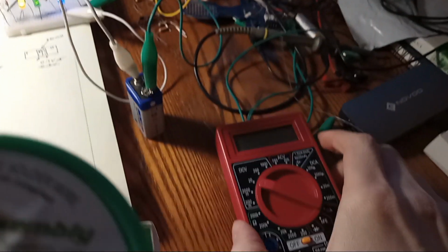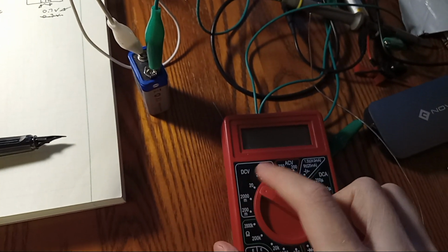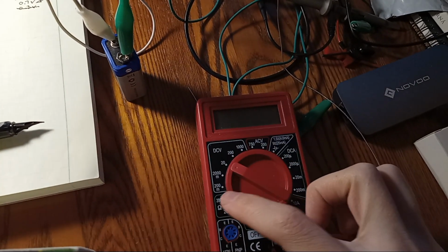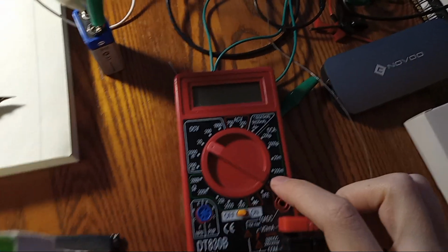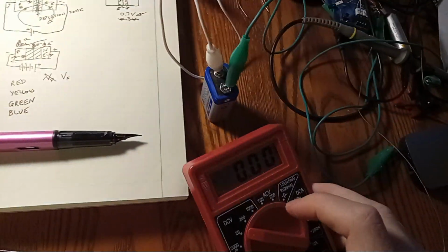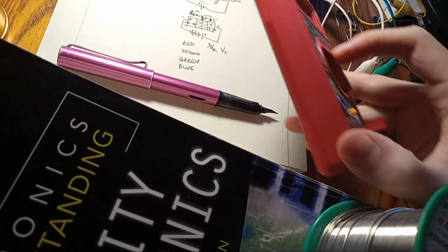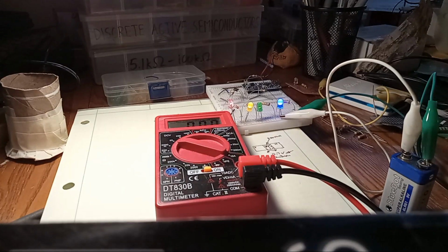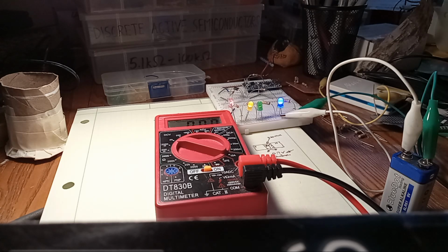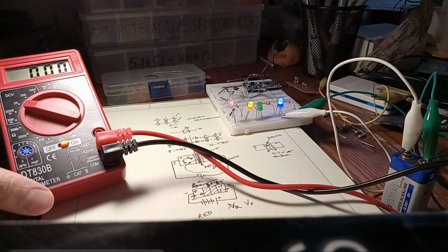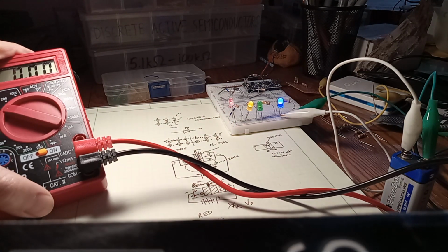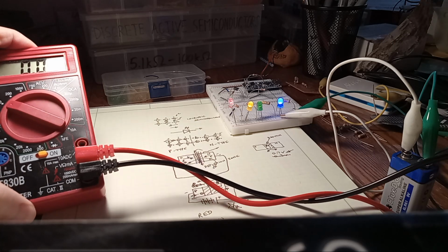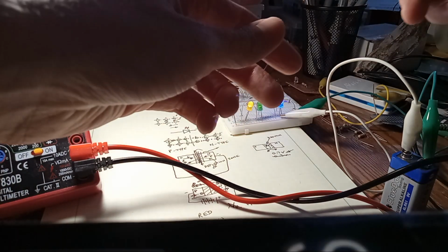To measure voltage with a multimeter, you set it to DC volts. Do not set it to ohms or you might damage the meter. Do not set it to amps or you might damage the meter. This one is already at the right setting for this, fortunately. So, let's cram some more things in here. And I see I'll need to use my hands to point the meter probes. Let's see. So there is a decimal point on this thing. You can't really see it very well. Now you can sort of see it.